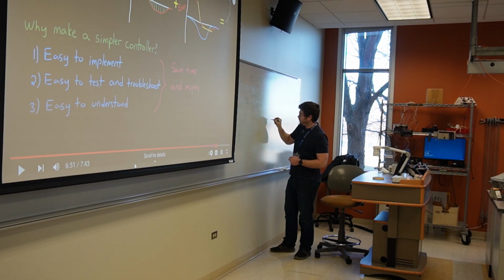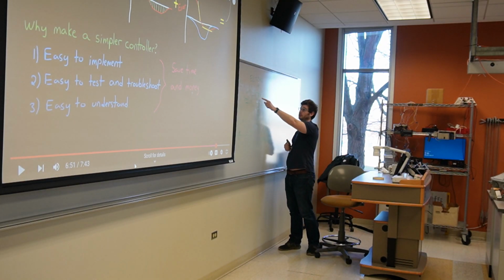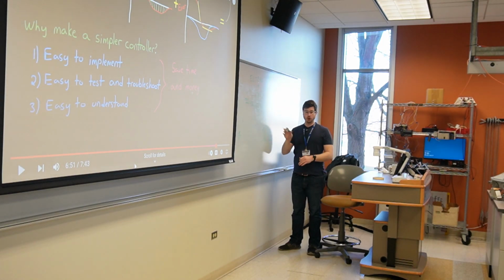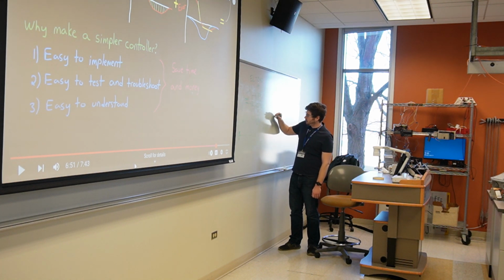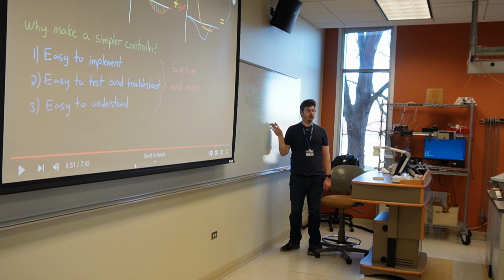If we zoom in on this, where we are and where we want to be are very, very close. But the P controller doesn't have any means to reduce this gap. It will always be this amount off, because it can't dynamically respond to this. It's sensing that we're here and moving accordingly, and the result of those two forces meeting is that small amount of error.